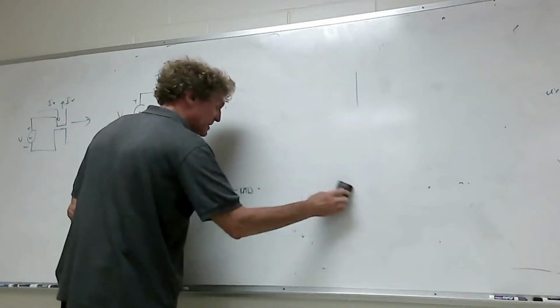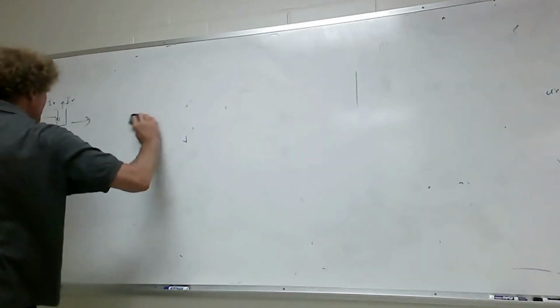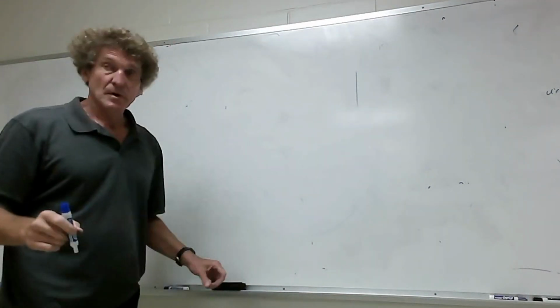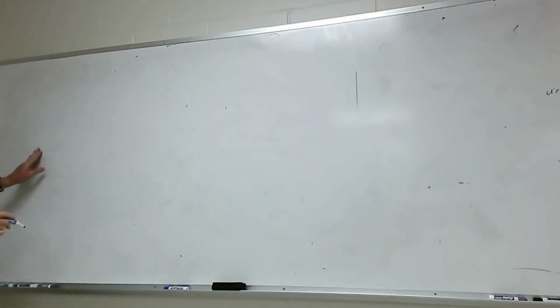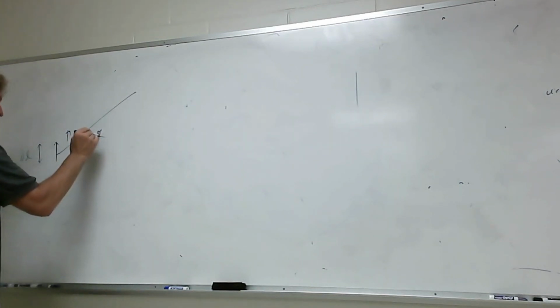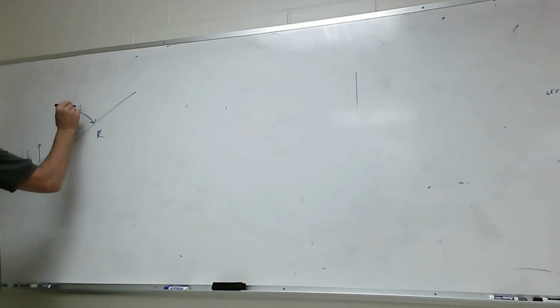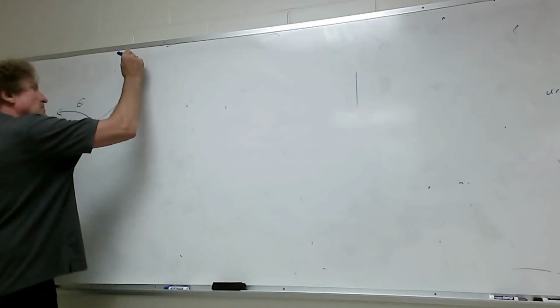Remember, this is just a short dipole. We've got the directivity, we've got the radiation resistance, we've got everything we need to talk about far field behavior from a short dipole. Now, there's one little thing I'm going to say. And we're going to use this to find out the electric field for any kind of straight wire antenna. When you have a differential current, say I have a current, but the thing just has a length of dl, and it's got a current I, and I'm a distance r away from it. Now assume that this thing is at the origin. And here's the angle, theta. Now we're in the far field still.